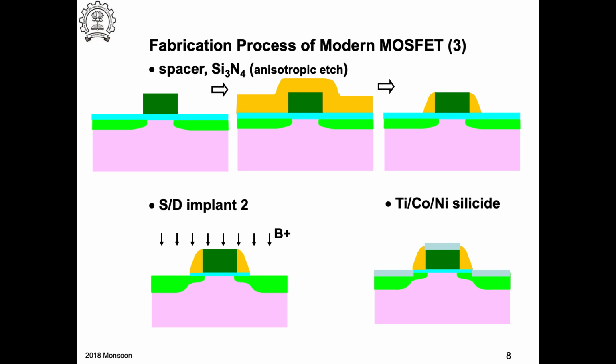So typically in silicon technology you use photoresist, but also sometimes whatever is there on the wafer, for example polysilicon, silicon oxide, silicon nitride, is a common material on the wafer when you do implantation. So these are the common masking materials.